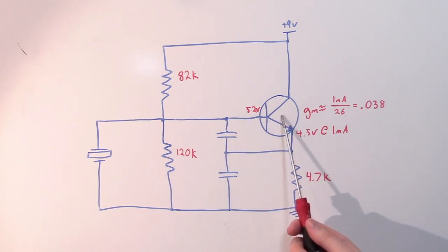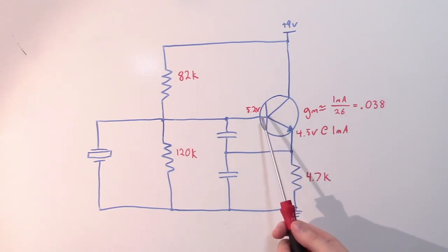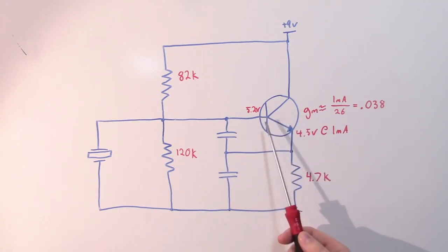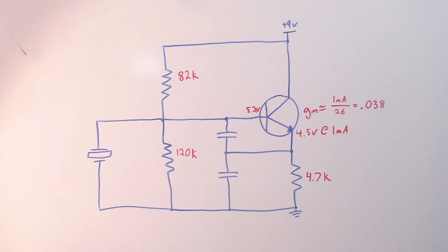Now I'm using a 2N3904 here, which has a typical base-emitter capacitance of 18 picofarads. So I'd want about 180 picofarads here, just so that this is really shunting out that capacitance effectively, and you're not really concerned with any small variations in that internal capacitance. Now I don't have a 180 picofarad cap on hand, so I'm going to use 150, close enough.